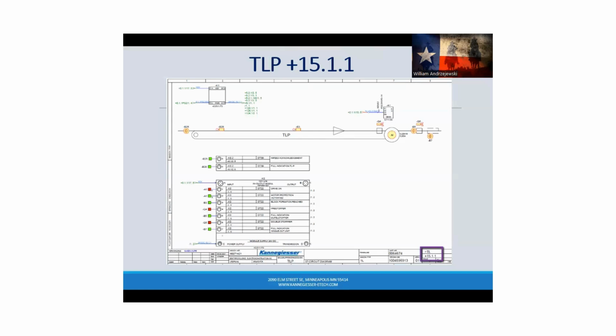The other thing that we're going to have is some type of stopping mechanism to prevent hangers from going forward, right? If this area over here says, hey, I'm full, don't send any more, well, I'm not going to stop my conveyor. Starting and stopping of motors undo wear. Okay, you get voltage surges. We just keep them running. We throw up a stopper, everything backs up, clears out down the road, drop the stopper, and everything can index out. Okay.